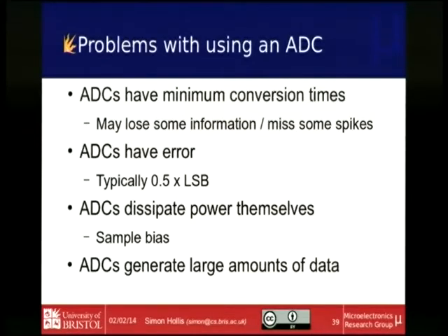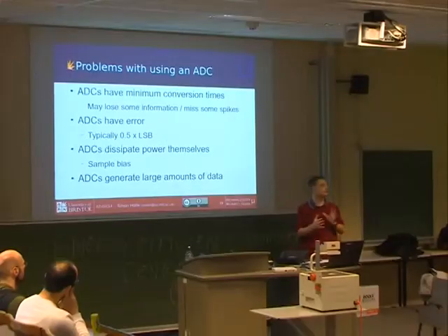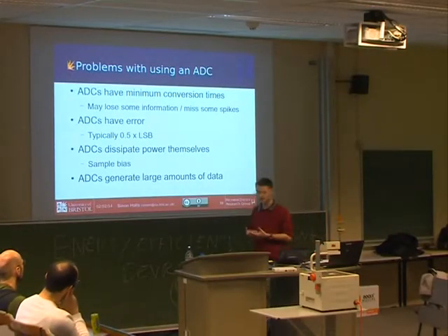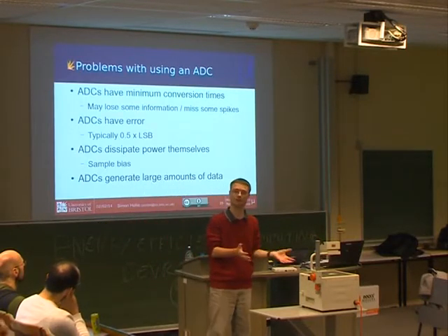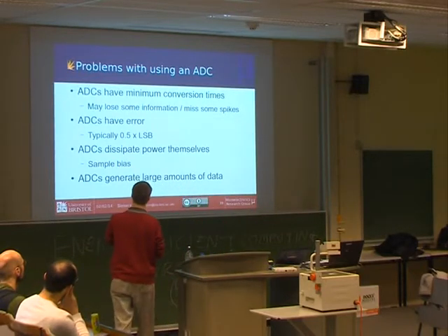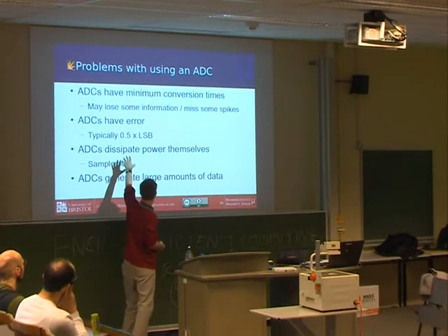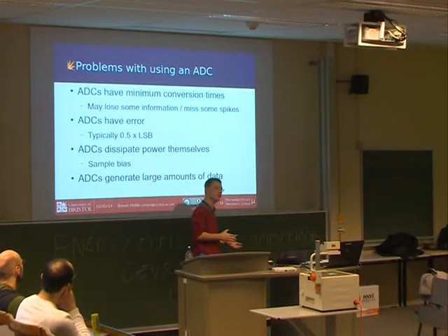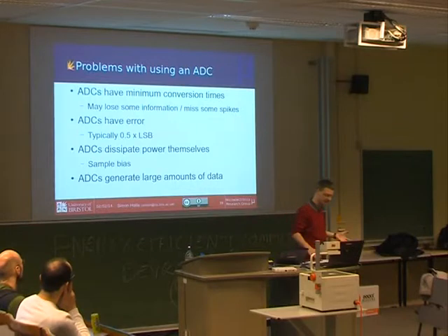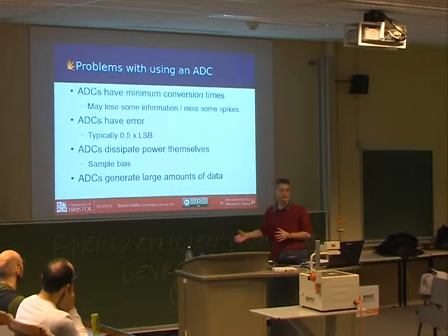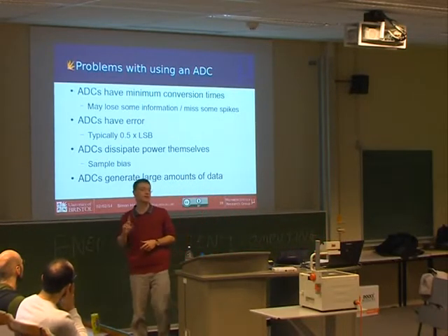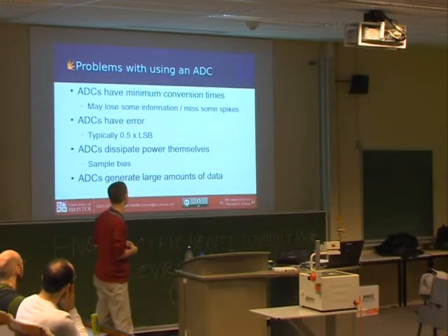You can buy a more expensive device and build a more expensive circuit. The other problem with this device is the analog to digital converter has a built-in error, because you're taking a continuous quantity, which is voltage, and producing a binary value, which has a fixed number of digits. So you can have error, and that's almost always half of a bit. When you take a value out of a measurement, you should basically discard the least significant bit, or at least average it over multiple cycles, because that will essentially randomly flip, depending on exactly how your ADC operates.